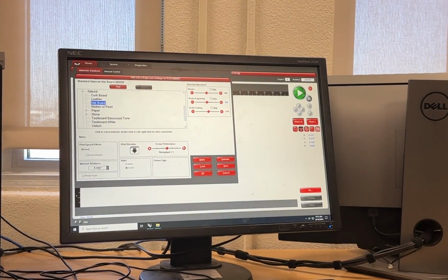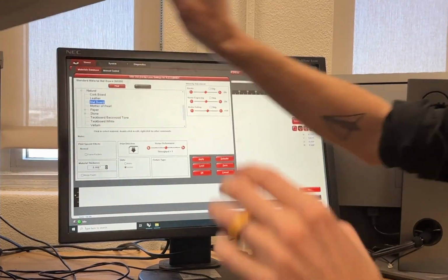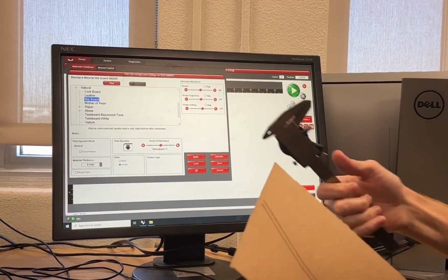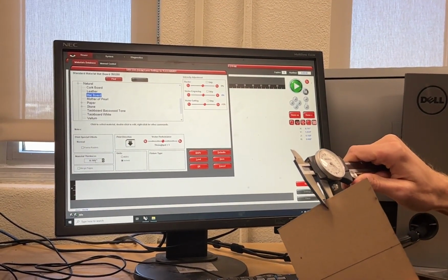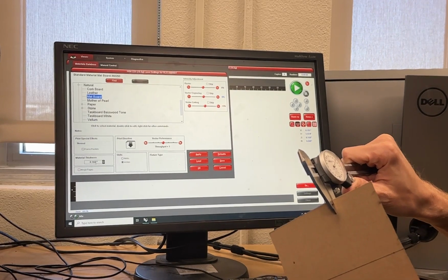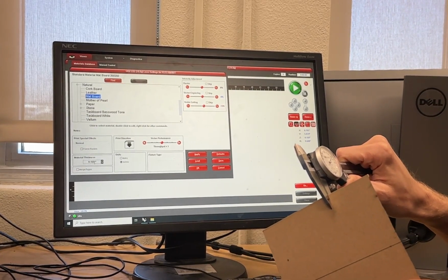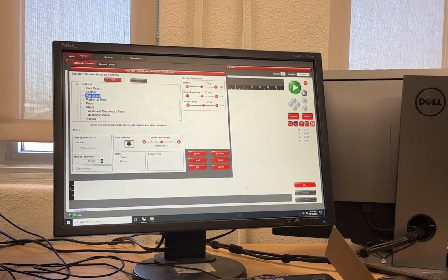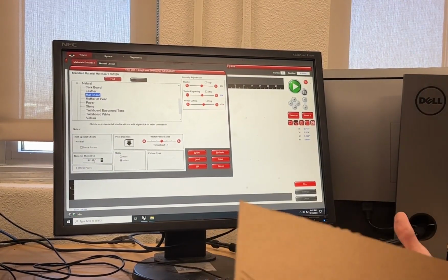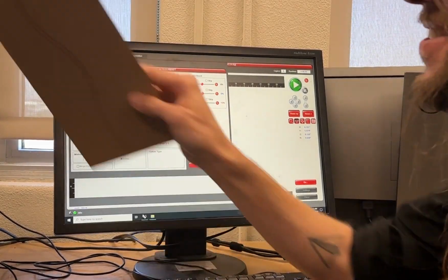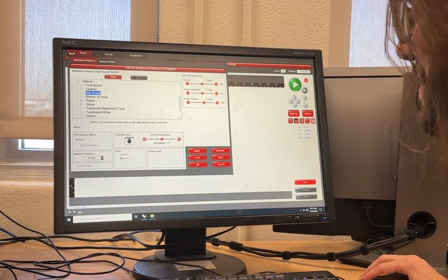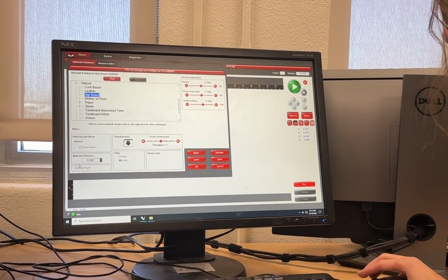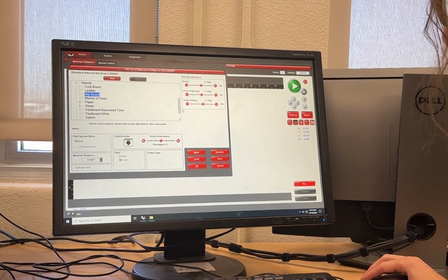So in our case, I can use my caliper, make sure that I have the right thickness here. You'll notice that it's in inches, so I may need to do a conversion. Again, we don't have the best tools here at SAC, but it's exactly 3 millimeters, I think, 2.8. 2.8 millimeters into inches. I guess we could do that in Google, but for the sake of time, I'm just going to assume that 0.160 of an inch is actually pretty close. I think it is. But anyway.